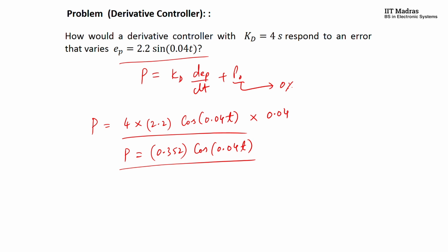Okay. So let's quickly revise what is an integral control and what is a derivative control. Integral control action, the advantage is that as long as the error exists, you keep on integrating, and therefore the control output increases or decreases continuously to make the error 0. Derivative control action, the advantage is that it can anticipate the changes in error, and since you are having d/dt multiplied by some gain Kd, if the anticipation is good, then depending on the slope, you take a control action.